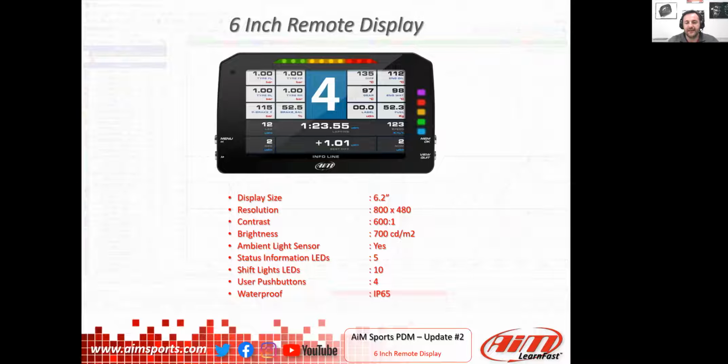Yeah, the 6-inch display is like the actual dashboard that we have in a 6-inch format. So we have the same resolution, 800 by 480. We have a high level of contrast, 600 to 1, and good brightness, 700 candelas. We have the light sensor inside because we can manage all the functionality that we have with the other dash. So we can change the brightness or the dash view from night to day situation or something else. This is very useful.